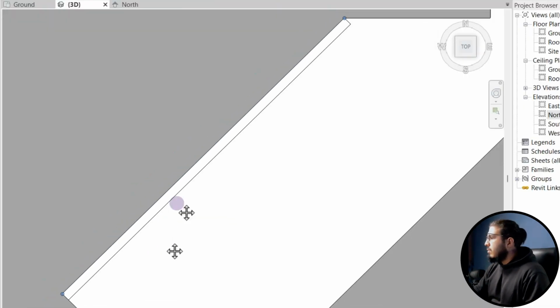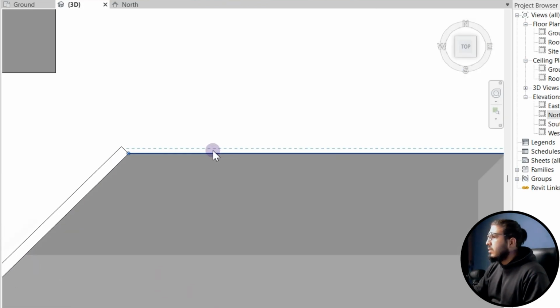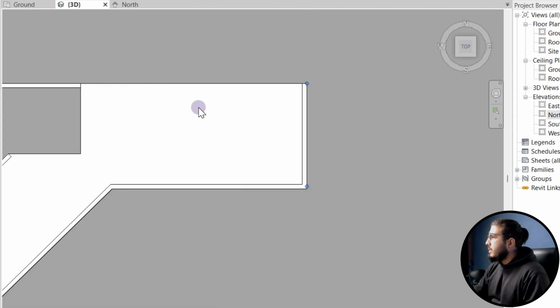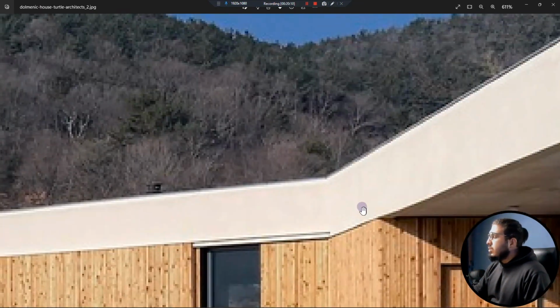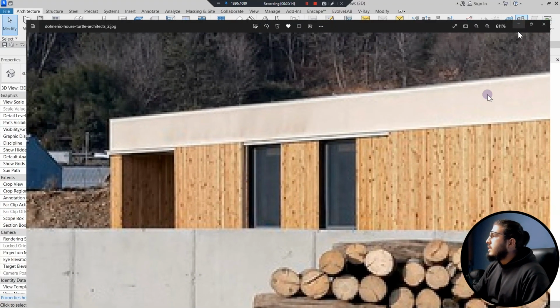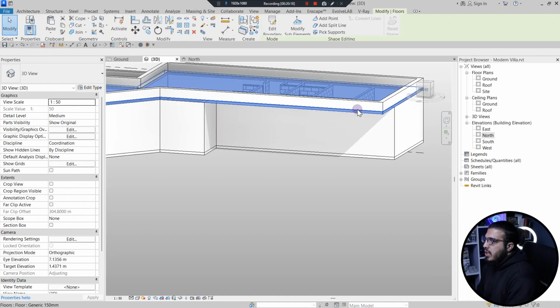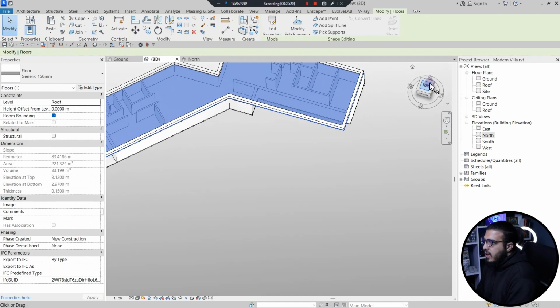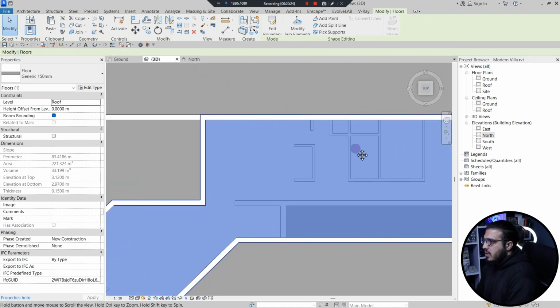Now we can create some walls in here to have our parapets. You can see in here we don't see the edge of the floor in here, so the thing that we need to do is to bring the floor to an interior side of the wall, and then we have to give it a minus offset to our floors.